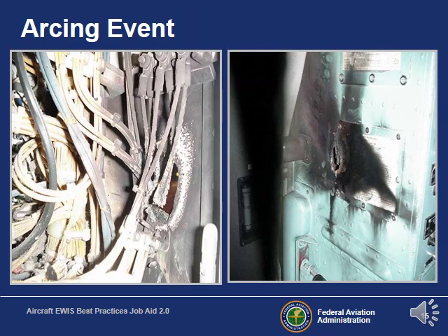And another problem is arcing. In this situation, notice here this airworthiness certificate. This airworthiness certificate was actually moved to this present location, and the mechanics installed the airworthiness certificate by screwing it into the bulkhead. Unfortunately, they didn't look behind the bulkhead, where there were a few different wires, and these power feeder wires were drilled into, and then there was some arcing. So, sad day for those guys.